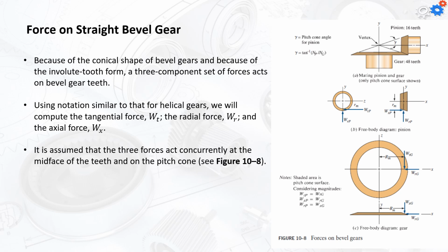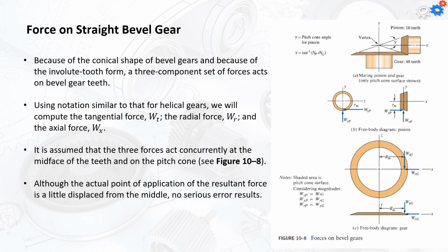It's assumed that the three forces act concurrently at the midface of the teeth and on the pitch cone, as shown in figure 8-10. Although the actual point of application of the resultant force is a little displaced from the middle, no serious error will result if we consider it to be exactly in the middle.